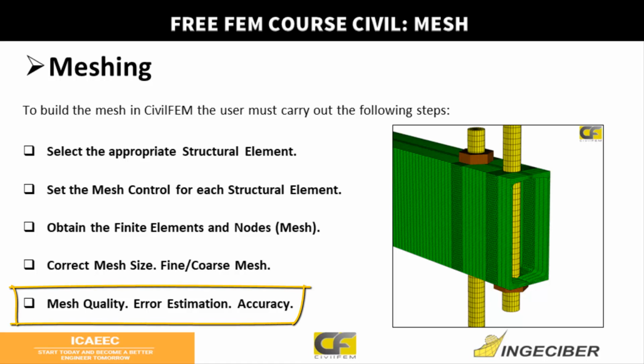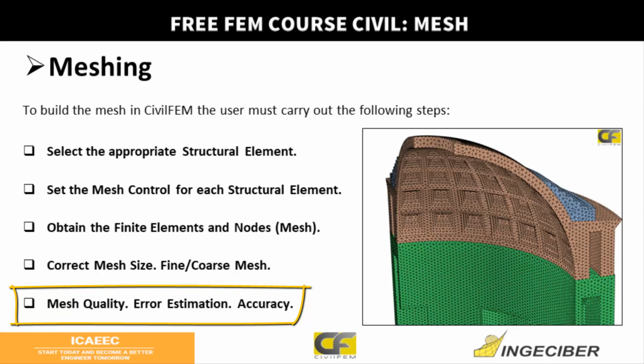Usually in the beginning it will be a hit and miss procedure, because in the beginning we don't know if we have a big or small error in our results, so we have to always take some time setting the correct mesh size, and even if we want elements of higher order, we'll see that later.